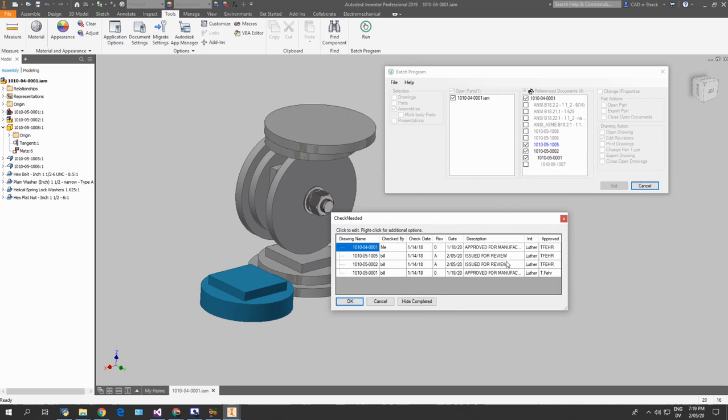And so here we have our list of revisions, and I'd mentioned before, but make sure if you want to edit these, the descriptions here are located in your settings menu, and they must correlate to what your drawings show. Otherwise, that column will be blank or it won't update correctly. So these edits, as you'd expect, you can also right click and get options here, so you can apply your values to all the columns just so you can speed up that process.